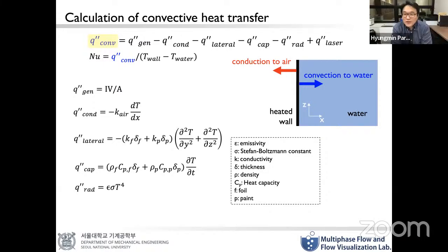Sure, because the sideways motion can mix the upper layer very well. Yeah, that's correct. Your understanding is perfectly correct, because as I said, in our specific configuration we have a large tank compared to the bubble plume width. We have two initially separated liquids that eventually you want to mix. That is our definition of the problem.